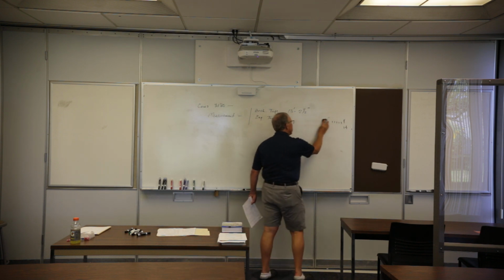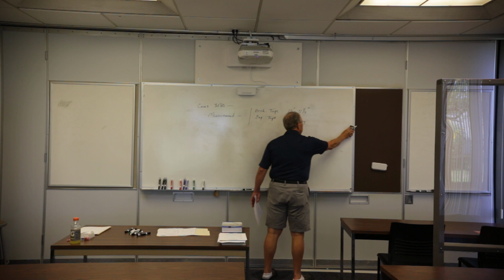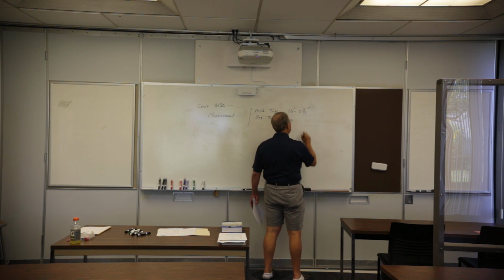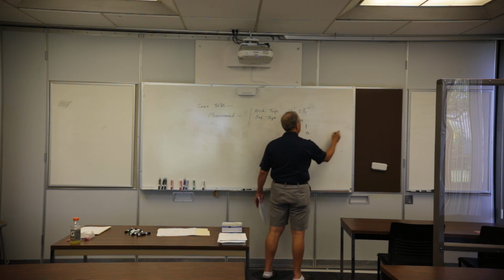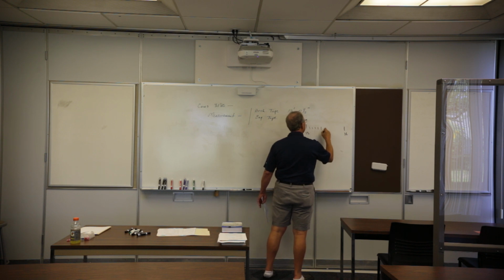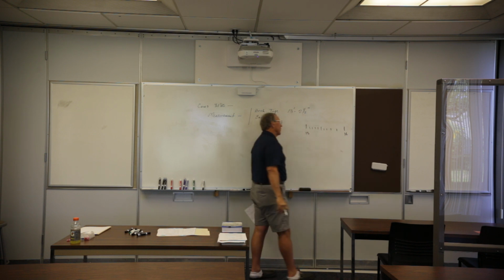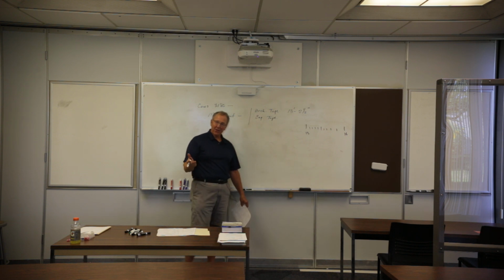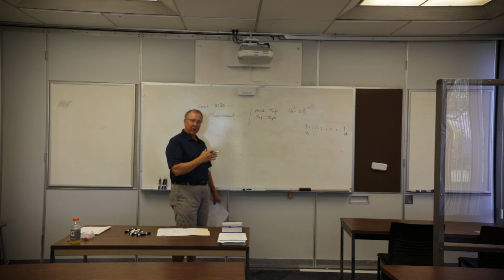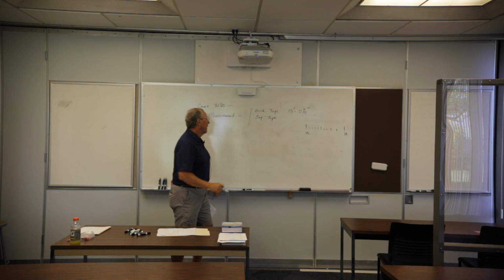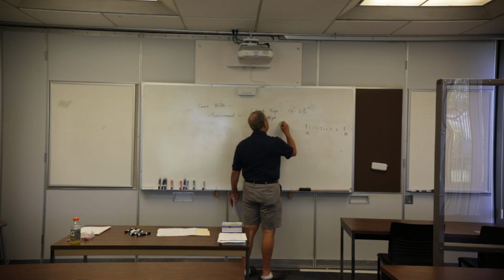As opposed to an engineer's tape. An engineer's tape has 1, 2, 3, 4, 5, 6, 7, 8, 9. It's going to have tenths. It's going to divide that foot into 10 parts. And if we would do that, 13.20 feet.